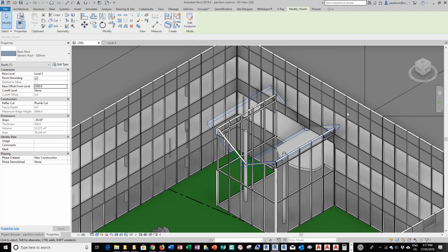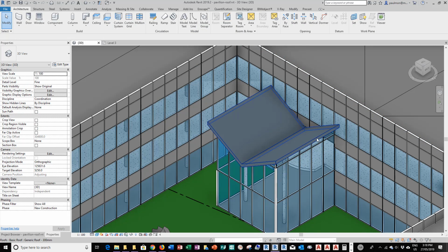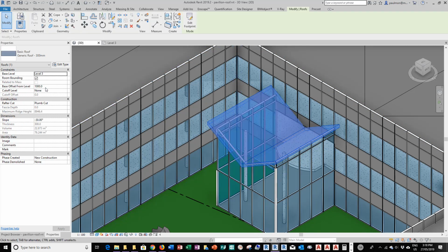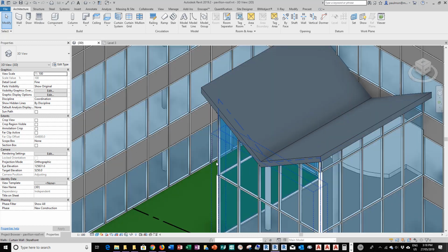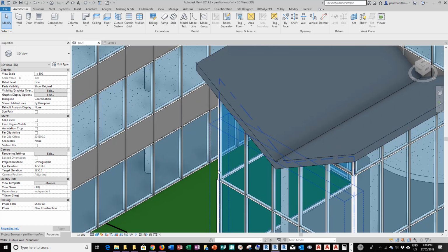And you can see that it just covers up the opening. Maybe we give it a little bit more, so we're going to change it to 1.2 meter. And now since we extended it up, we might need to do some cleaning up on the mullions that we previously did, because you see the quad mullion only extended to the base level, so we need to clean this up.